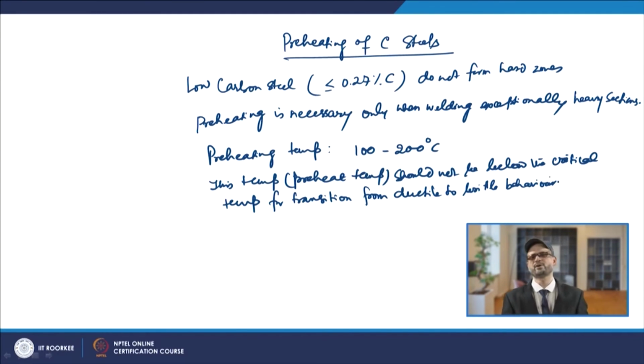So, particularly this is important when we are doing the welding in the winter. We have to be careful, because many times we have the danger of having cracks under the influence of these welding stress values. If the impact strength becomes small, so your notch impact values are under the alarming level, then it will be failing. If the notch impact value goes below 8 to 10 joule, there will be a problem.